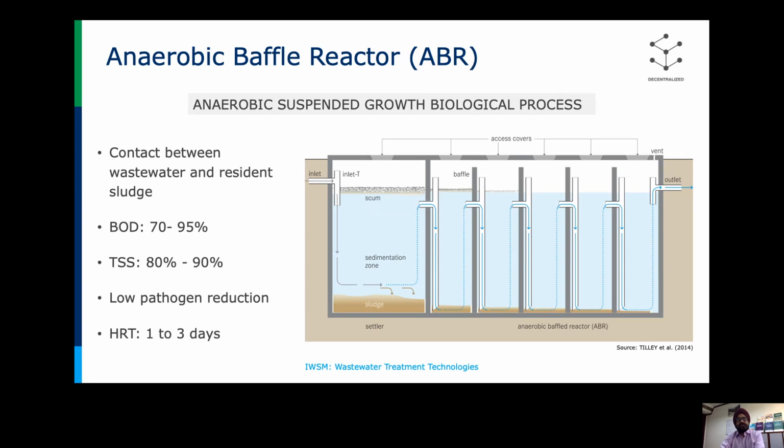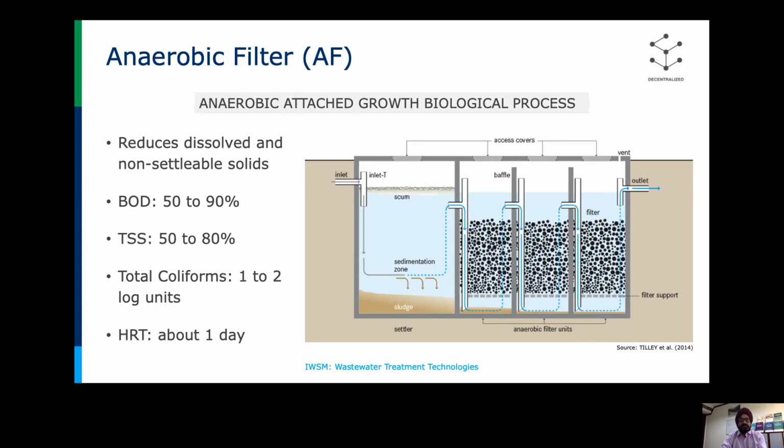So this is a typical anaerobic baffle reactor, which does treatment for BOD and TSS and has a hydraulic retention time, or water retention time, of 1 to 3 days. It does require 1 to 3 days to do treatment for BOD up to 70 to 90% and for TSS from 80 to 90%. Next is the anaerobic attached growth biological process. So this is again anaerobic, like the previous slide. The only difference here is you have filter medium attached in it.